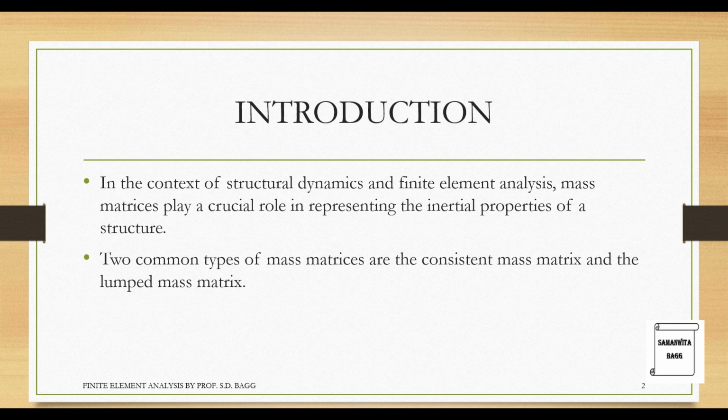If you consider that the mass is uniformly distributed over the body, you would say that you are going for consistent mass matrix analysis. But suppose you assume that the entire mass of the beam is divided into half and each half is placed at the two ends of the beam, then we will call it lumped mass matrix.